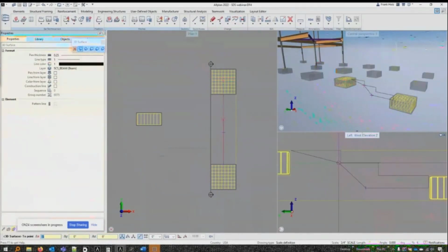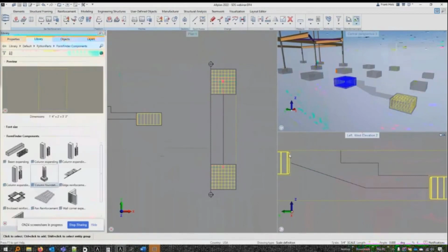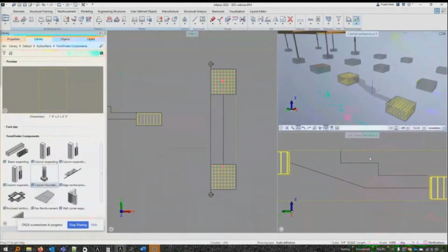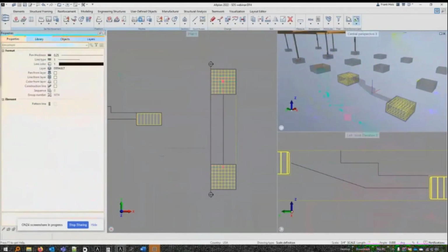I'm going to come up to the next step here, and I'm going to do the same thing, 1 foot over, 1 foot down. But at this point, I'm actually going to create a new track point. So I'll just add that as an extension point, and now I can extend along that line and go up any number of spaces, or I just have a couple of steps here, so I just terminate at that end where I need to. Now that I have that 2D surface in space, I'm going to go ahead and extrude that.